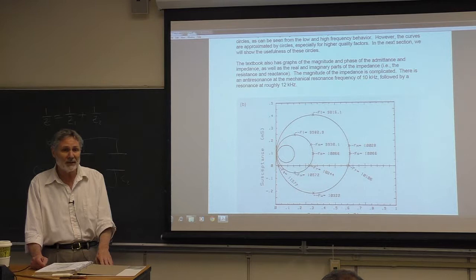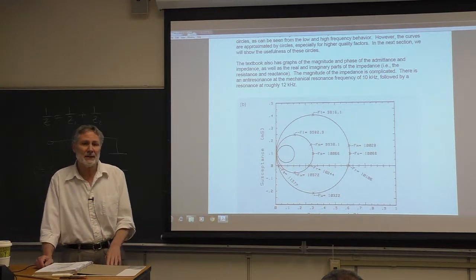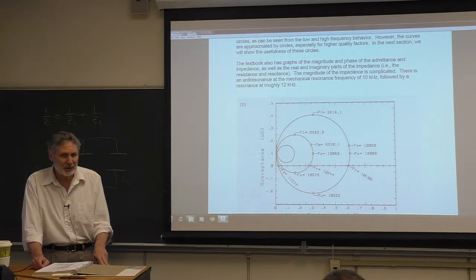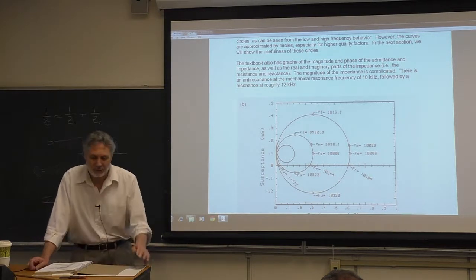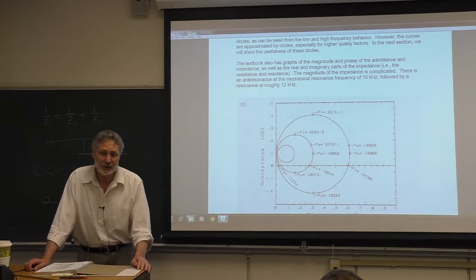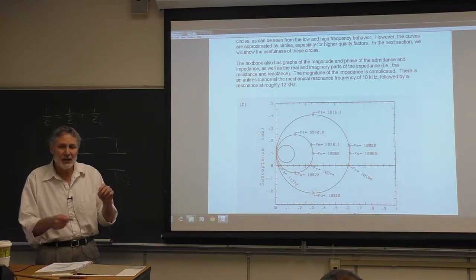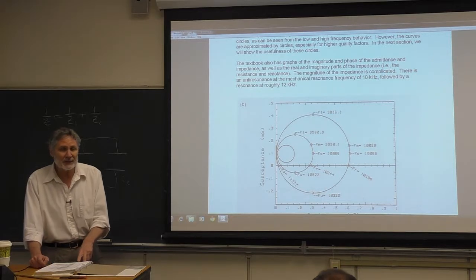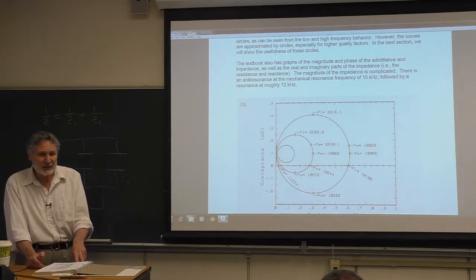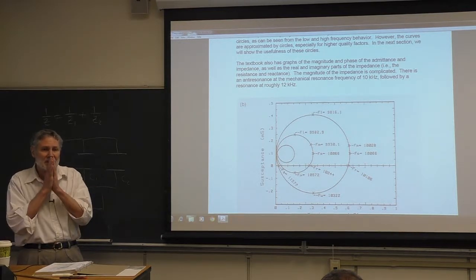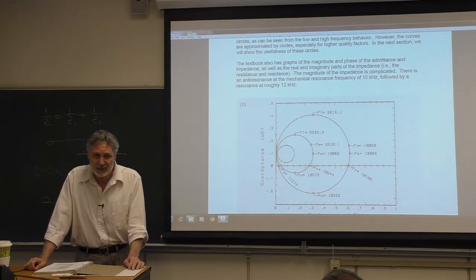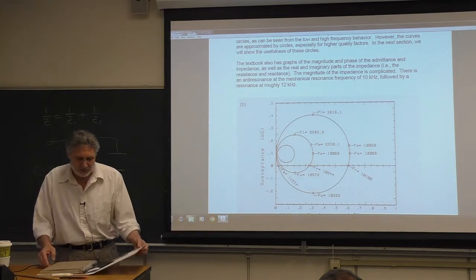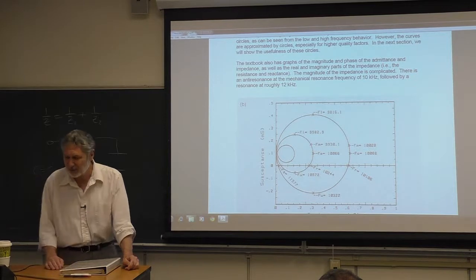But you have to be careful. You have to think what a short is and what it corresponds to, right? A shorted capacitor, which is what kind of capacitance? Infinite capacitance is like a short. Zero capacitance is like an open circuit. You've got to make sure you use the corresponding mechanical part, and it's the compliance. So an infinite capacitance is something that's infinitely compliant. That means the spring's not there at all. It's broke, you've cut it. The opposite case is like a rigid rod, very stiff. So you need to be careful with that. I edited the quiz for next year. Hopefully, maybe it'll help.